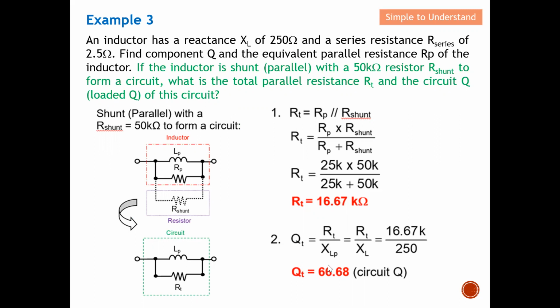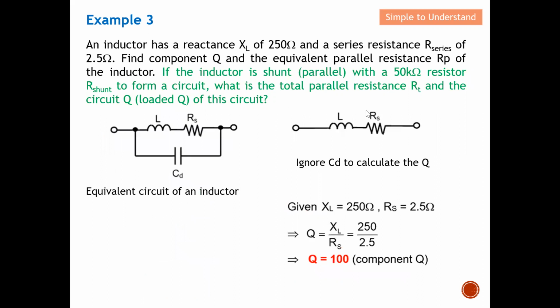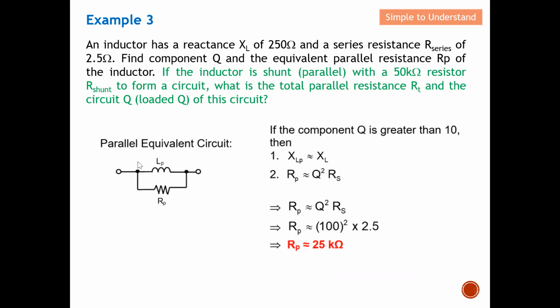With this, I'd like to end my discussion. Over here, you can see that the three parameters, for example the radius, the length, and also the number of turns, will indicate the value of the inductor. In this example, I have done a quick conversion. By right, the equivalent circuit of an inductor looks like this. I omitted my distributed capacitor, which results in this equivalent circuit of an inductor. Over here, I have shown you how to convert a series resistor into a parallel resistor, so this becomes the resultant parallel equivalent circuit of an inductor.